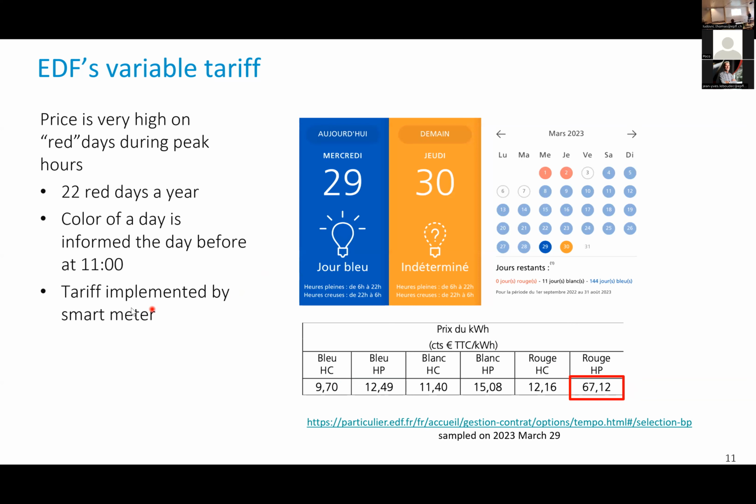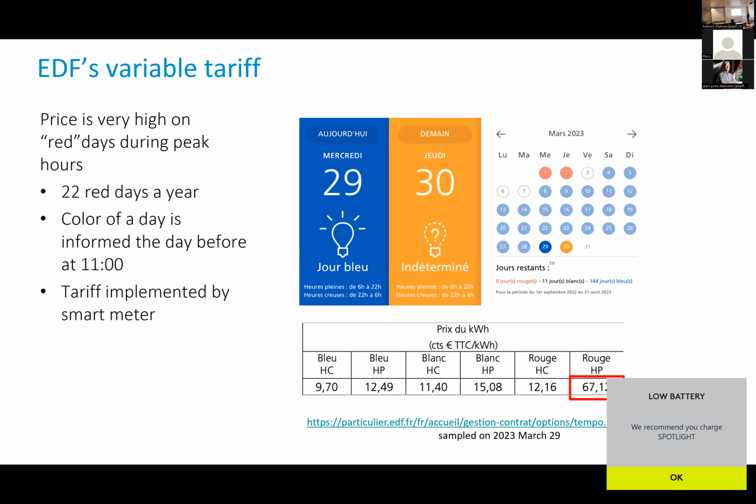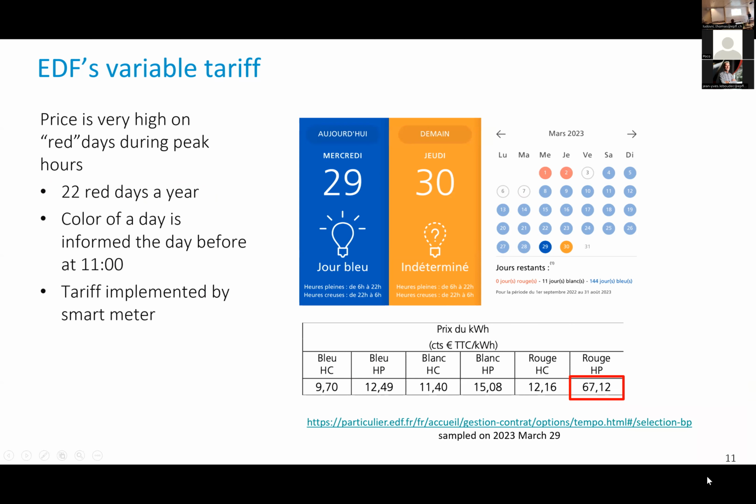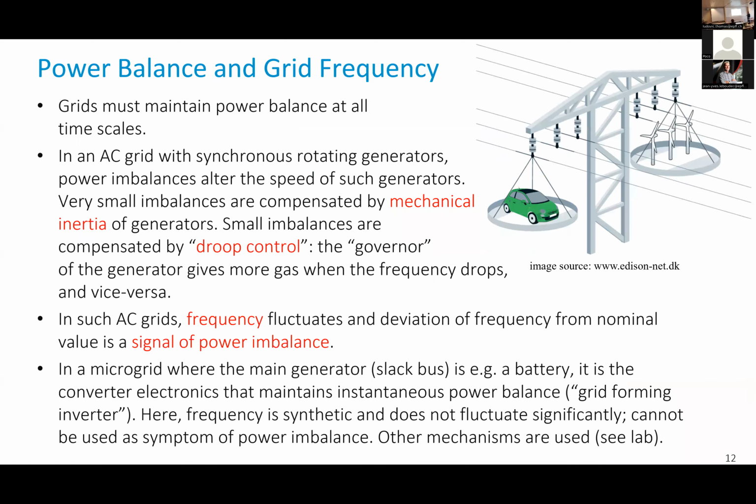And this is possible because we have smart meters. It's possible because now we can control the price and change the price with some flexibility. Here, the flexibility is on the energy provider side, and here too you have some limits on how many days it can happen in a year, and that's one way. And we were told that it was effective in reducing the peak. This winter is the first winter when it has been introduced. That's a fairly coarse implementation of demand response.